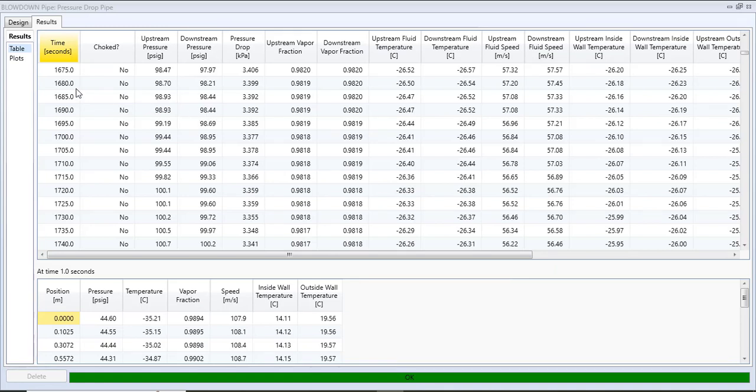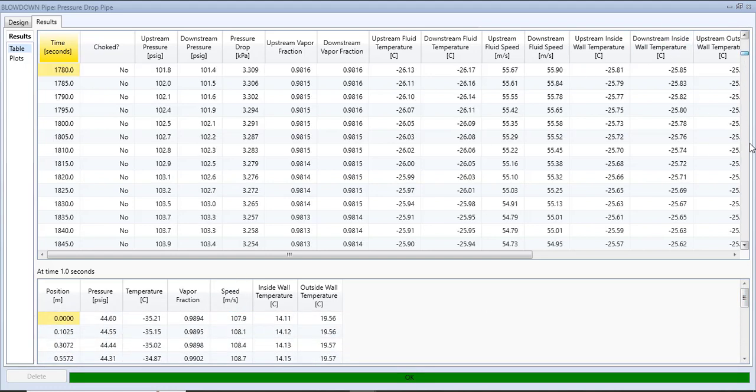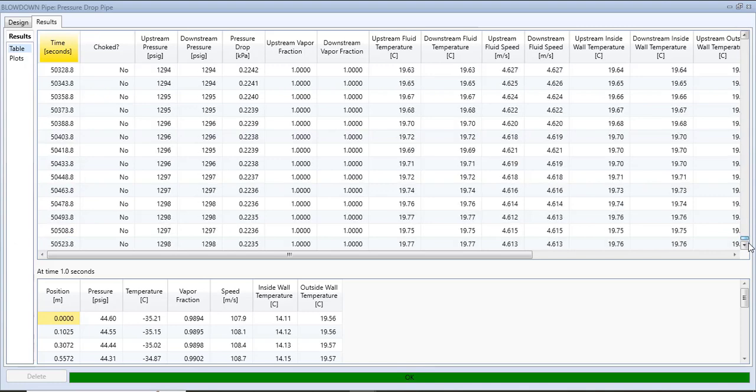As you see, in the pressure drop the length we specify was around 1.5 meters, and each interval is showing how much the speed is. This is showing at each second, and if you click on each second, it will open one more tab for each time second across the length of the pipe that we have specified, 2 meters, to see how things are. You can see the velocities start at around 100 meters per second, and at the end it will be around 8, 9, or the normal velocities you get during steady state. So this is pipeline pressurization.